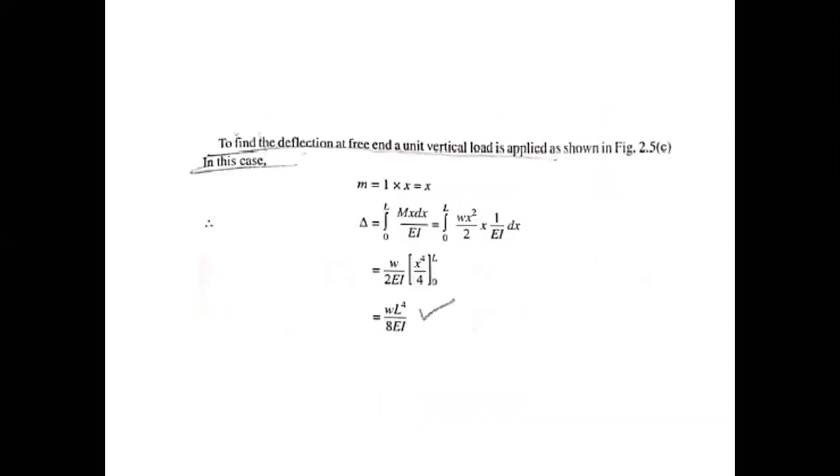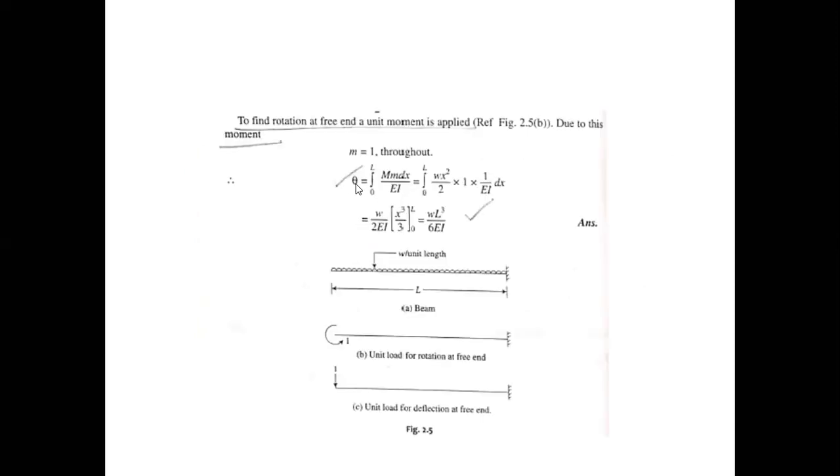So again, for the same equation, if we need to calculate the deflection, the deflection will be the moment multiplied by the perpendicular distance. That is, small m due to unit load; the unit load is 1 multiplied by x, that is x.